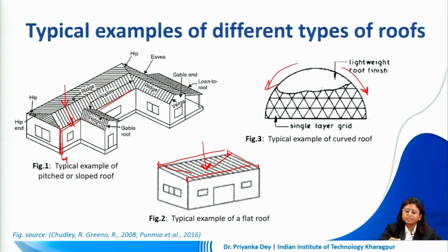There are ridges and valleys which are slopes created on the surface to ensure that the water flows in a certain direction and collects in the rainwater pipes that are provided in the corners. This is the storm water drainage that we provide to collect the rainwater and guide it to the drainage system. So that slope will ensure that the water will flow.